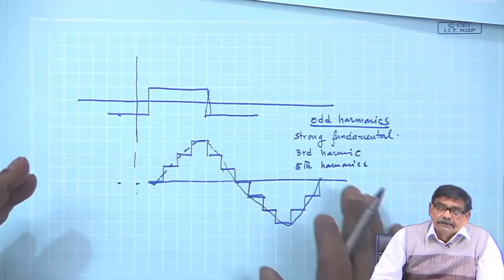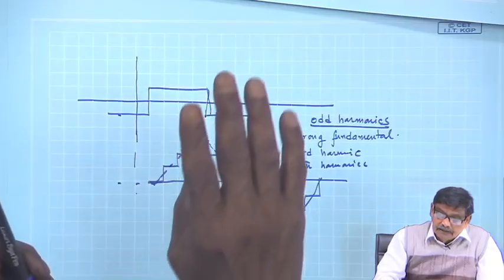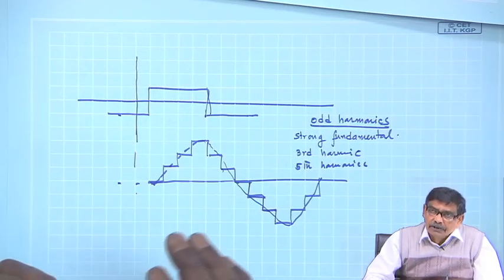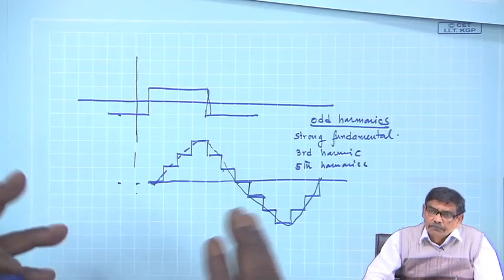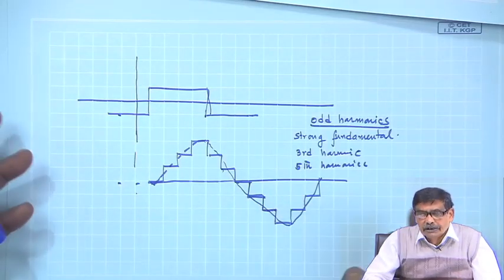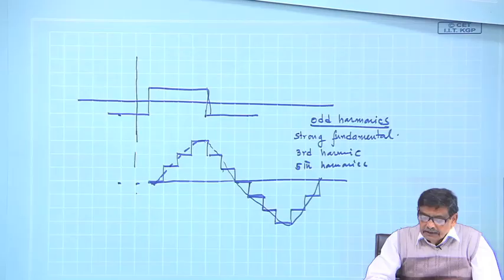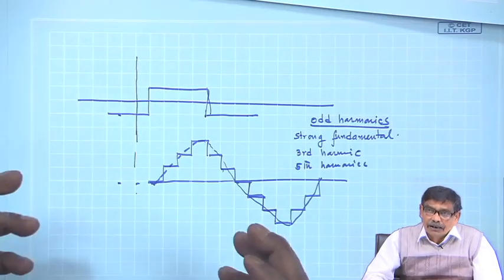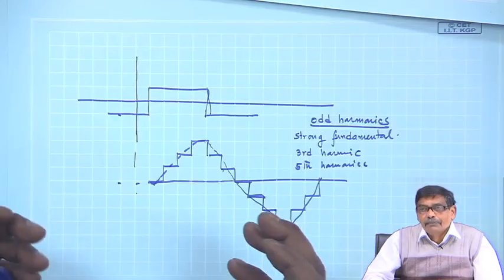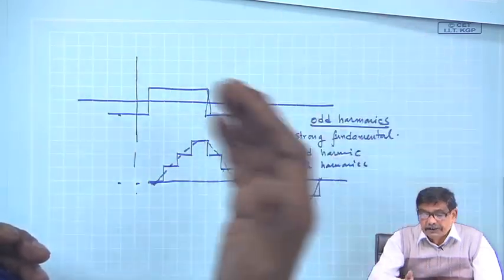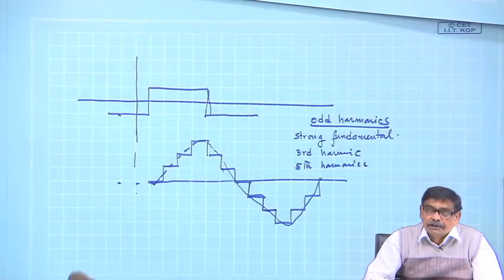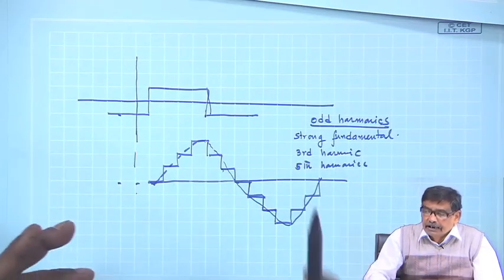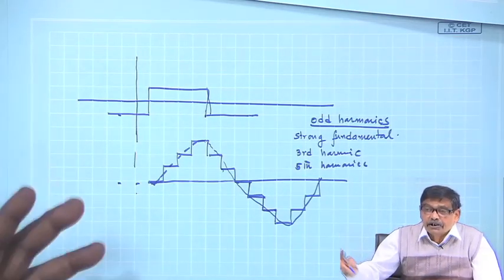in such a scenario, you have to construct a machine to have a sinusoidal B distribution. Why sinusoidal B distribution? Because you want to generate sinusoidal voltage. Therefore, using a single coil to have a space variation, theta variation of B sinusoidal, no, that is not possible. That is a pure rectangular square wave, like inverter output voltage.